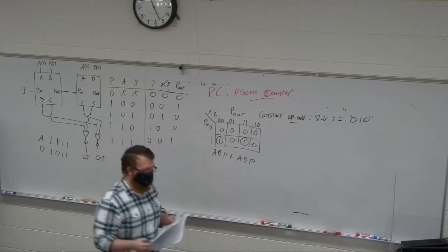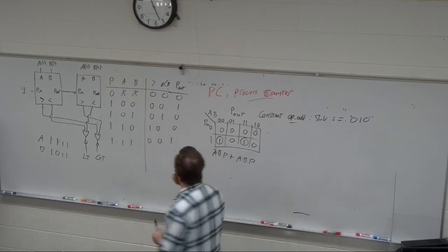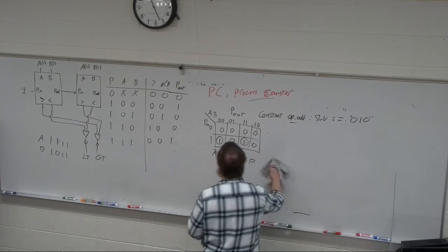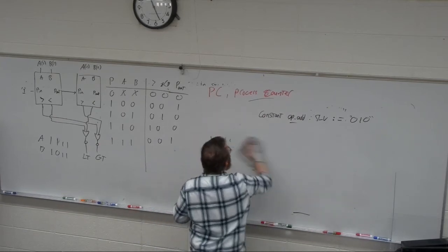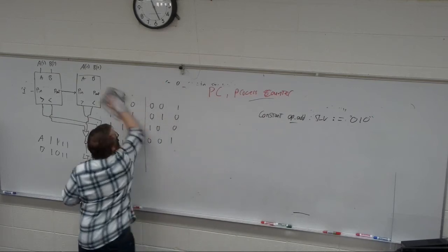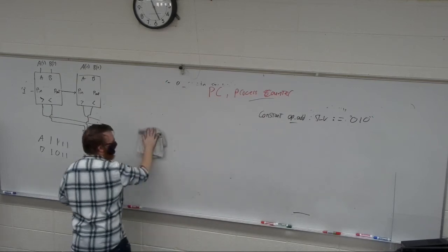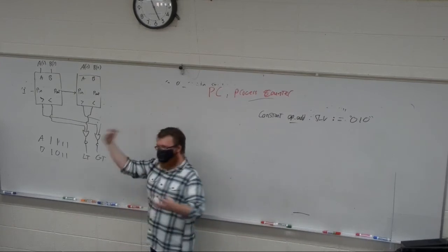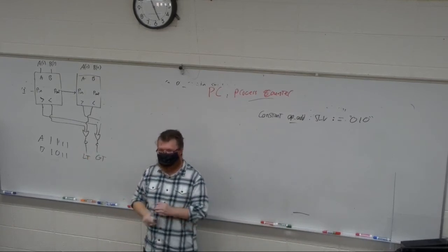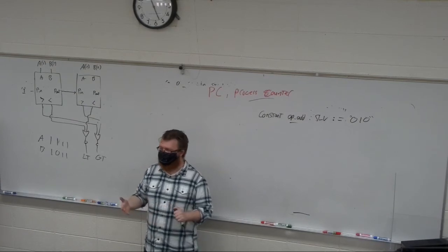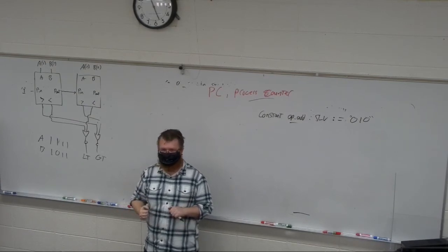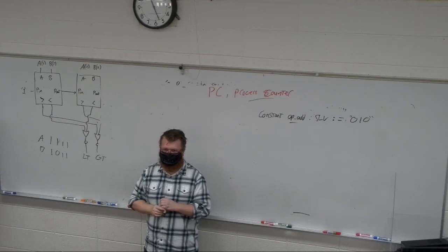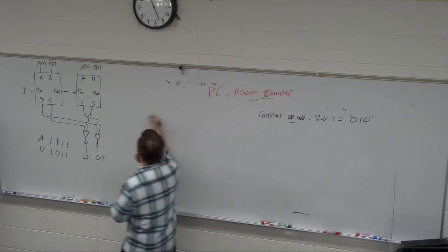So the main idea of the multiplexer that I think some people are struggling with, and we've asked this multiple times, right? If I have only 2-to-1 muxes and I need a 4-to-1 mux, I need to stick them together.